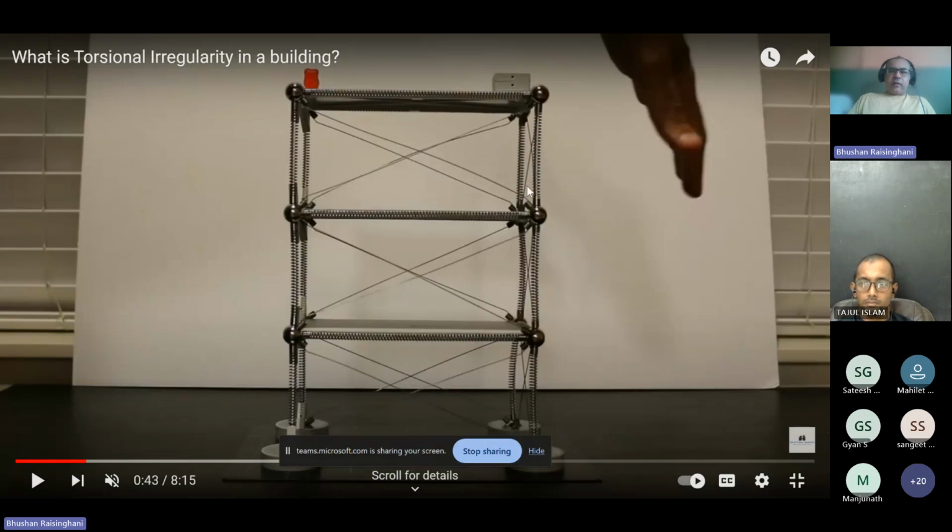Now they are going to shift the eccentricity of the load, and will demonstrate how you can make some modification in your structural system, that is size of the shear wall, orientation of the column, bracing if it is a steel structure. So they are trying to regulate the stiffness between the two frames so that the torsional irregularity is reduced basically.